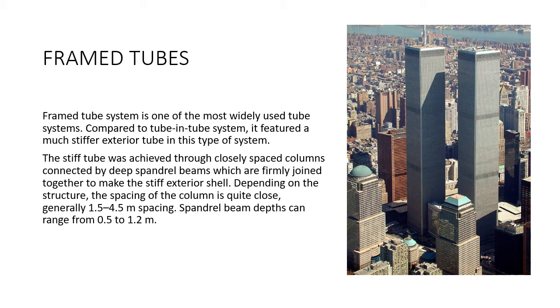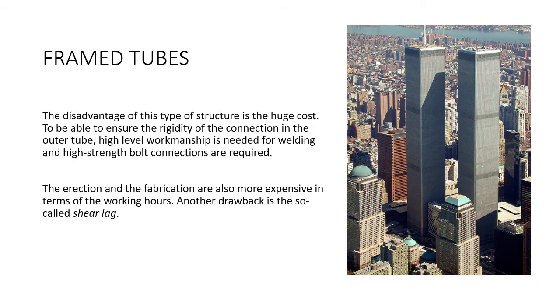Depending on the structure, the spacing of the columns is quite close, generally 1.5 to 4.5 meters. Spandrel beam depths can range from 0.5 to 1.2 meters. The disadvantage of this type of structure is the huge cost.